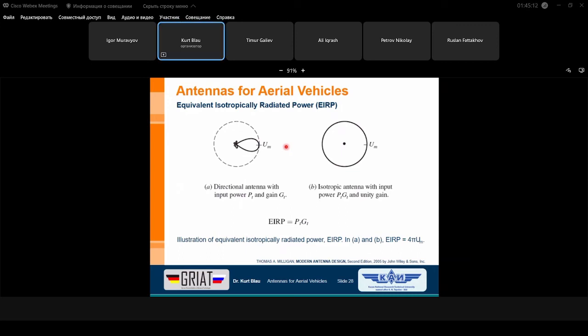Because the antenna has a 6 dB gain, it is not identical with an isotropic radiator, but we don't know in which direction the antenna can radiate, and so we have to assume the antenna acts like an isotropic radiator, because it can deliver the energy in this direction, this or this direction. And this is, let's say, only a safety measure, a safety figure of merit. And so we have to do the opposite.